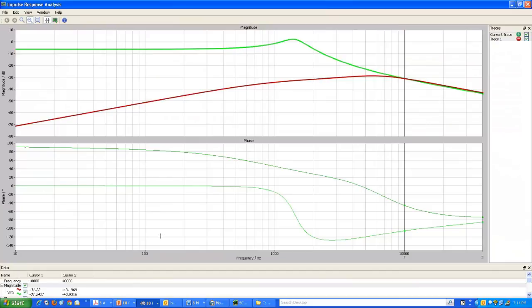Okay, so 100 Hertz is here, so you want somewhere in this frequency range the gain to be small, and you can see that the closed loop improves that performance by about 40 dB or so. And as before with the output impedance case, beyond the crossover frequency, the closed loop controller cannot do much. The two disturbance transfer functions merge after the crossover frequency.